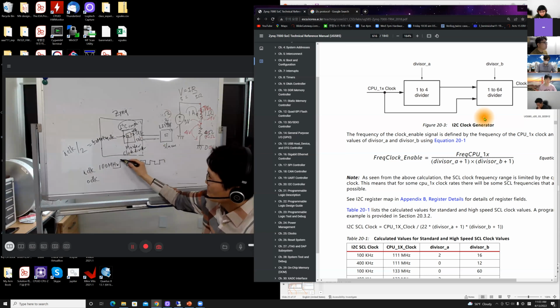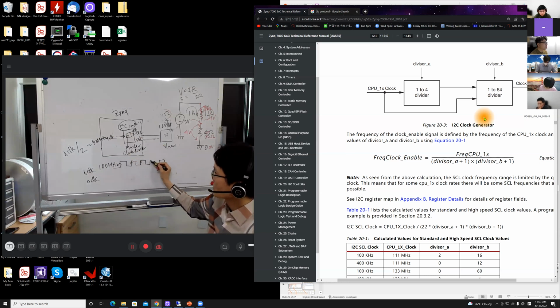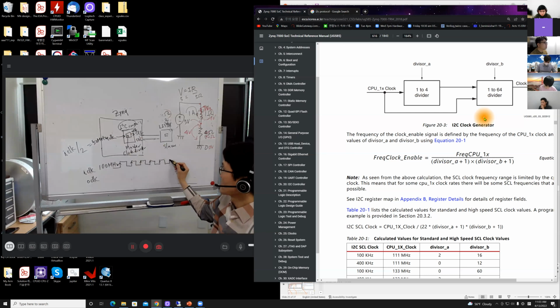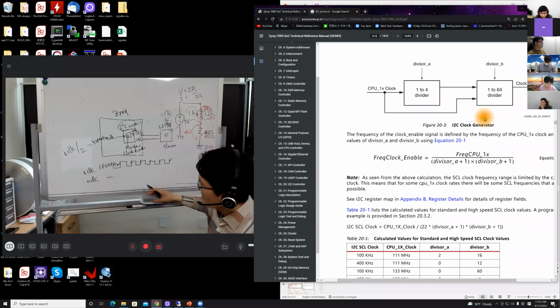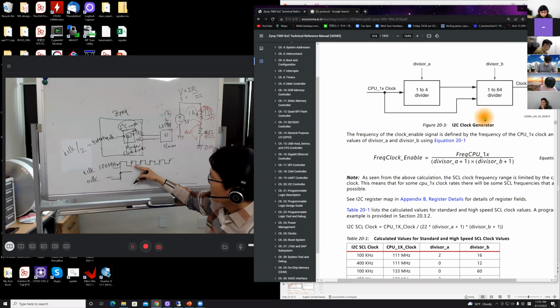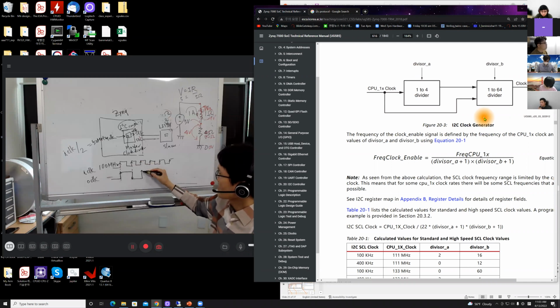Very simple. Every rising edge, you invert the signal, right? So here, for example, we don't know the first state, but let's assume 0. Then here you invert. At this time you invert, then invert. Rising edge, you are inverting. Rising edge, you are inverting. Next rising edge, you are inverting, and so on. Then you do the clock division operation.